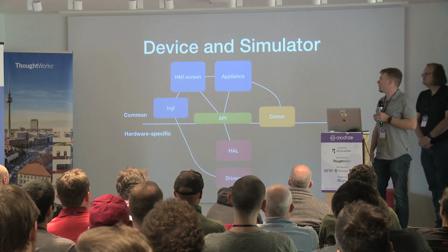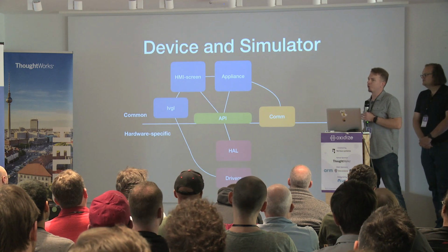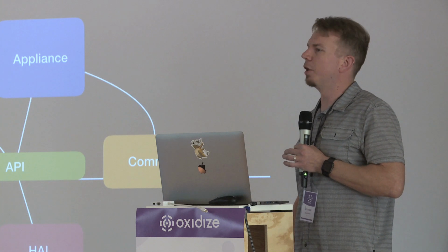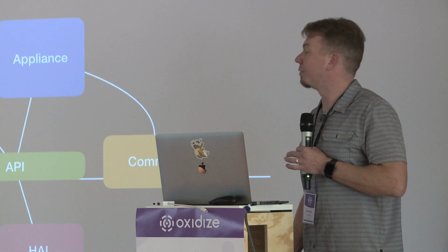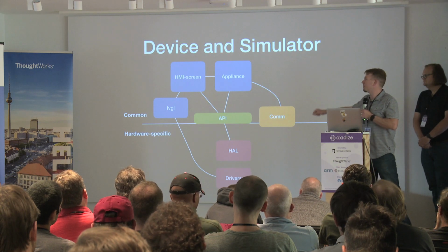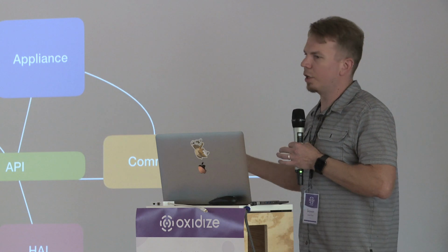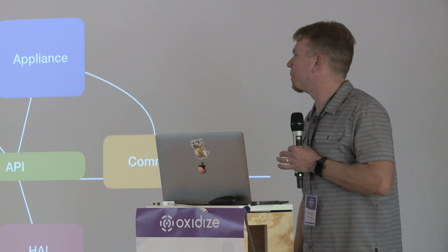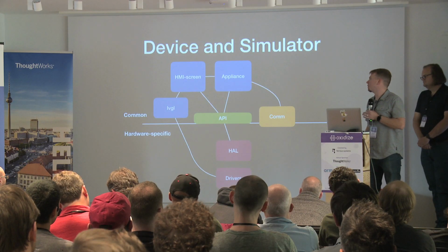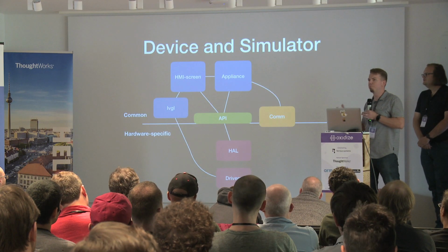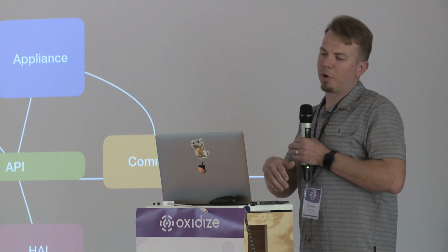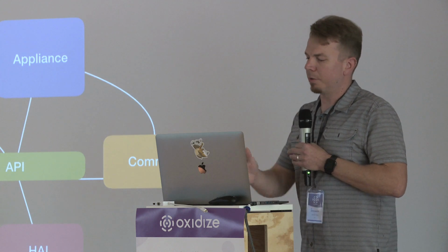This diagram illustrates what I was mentioning earlier about having a swappable HMI implementation. So one of the variants of our appliance that we're working on has a screen. And so for that, we swap out with this different HMI screen implementation and use LVGL, which is a package out there with a wrapper around it, to work with that screen and then hook the LVGL implementation up to either the frame buffer on the hardware itself or a frame buffer implementation in the simulator.